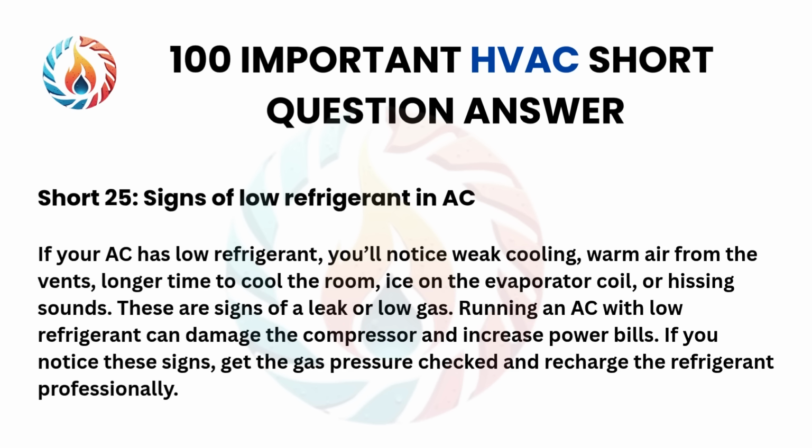Short 25. Signs of low refrigerant in AC. If your AC has low refrigerant, you'll notice weak cooling, warm air from the vents, longer time to cool the room, ice on the evaporator coil, or hissing sounds.